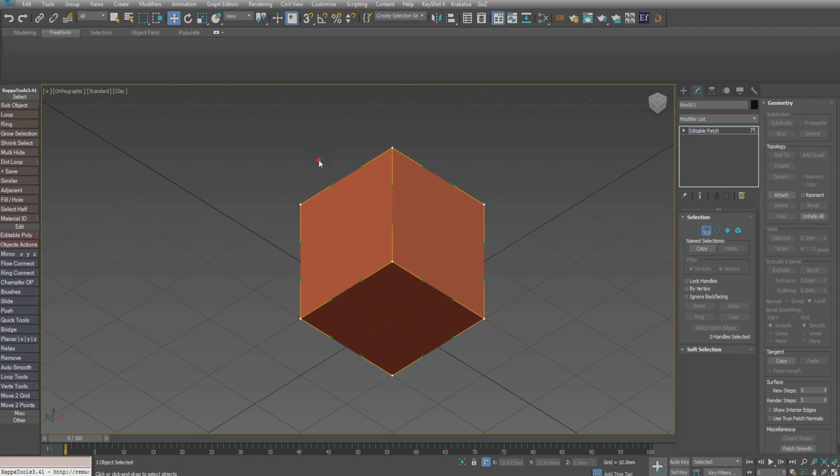So we'll go ahead and use the rectangular selection tool, and we'll just select these 2 handles on the outer edge. And down here in the Z parameter, we'll type in a value of -7. Alright, so just dash and then 7 and then hit enter, and you can see that that has bent the object along the border there.